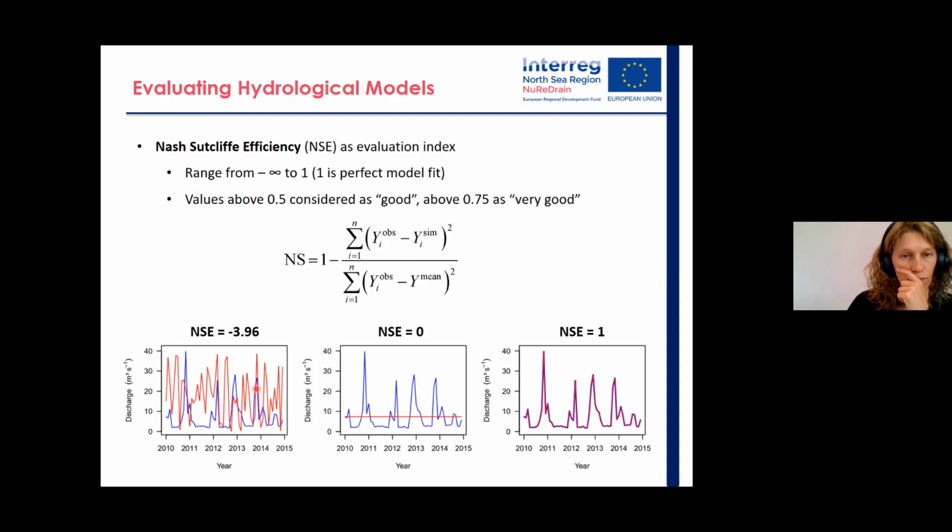So a negative NSE means we don't even need the model to describe our discharge. But we have to emphasize that indexes like the Nash-Sutcliffe efficiency are not solely suitable for the evaluation of models. You also always need to consider flow components and the general behavior of the model and the parameterization. So you need, let's say, special knowledge to evaluate the model quality.